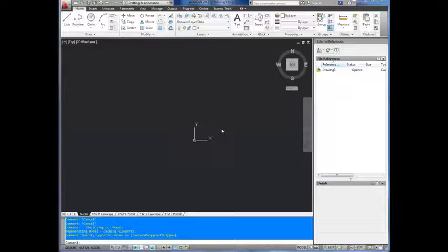In this video, I'm going to show you how to insert property lines that I've downloaded from a city website, and then I'm going to show you how to use a Google image and georeference it using the align command to overlay underneath of those property lines. So let's get started. Here we go.